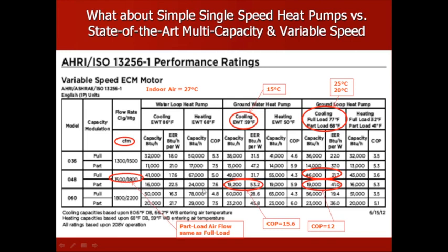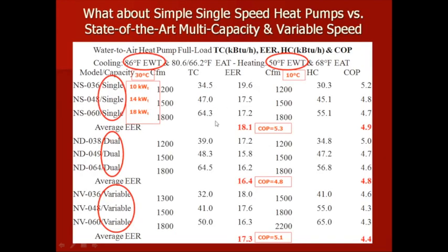These machines are also rated at part load, where the conditions are very mild, and you can see here that they rate the machines at part load capacity but with full airflow. So it's a very misleading set of things.